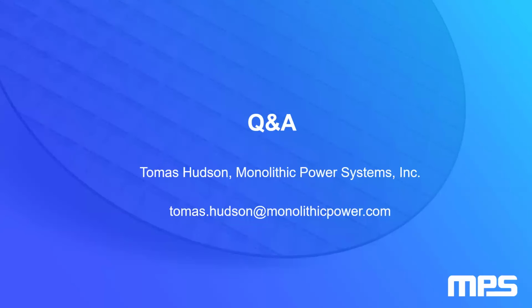Yes, I was thinking of THD more linked to the input filter design. But yes, THD generally is a worry in AC/DC power supplies that have to go back to the network. In the systems we're working with, we would come from a DC bus that's already been regulated. These are point of load converters just before the FPGA.